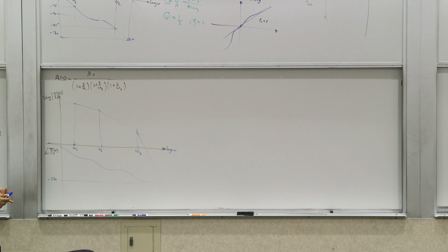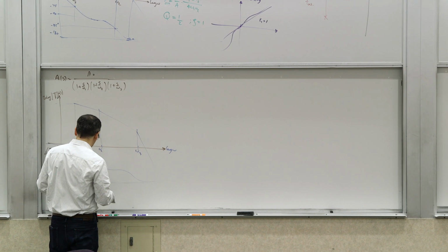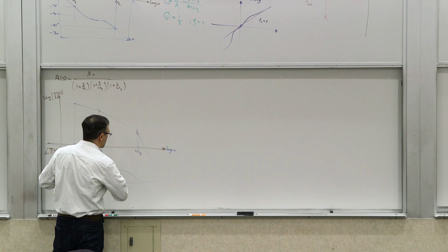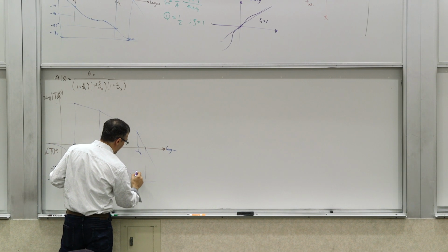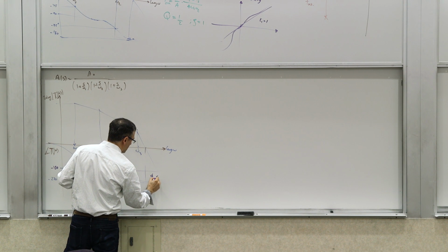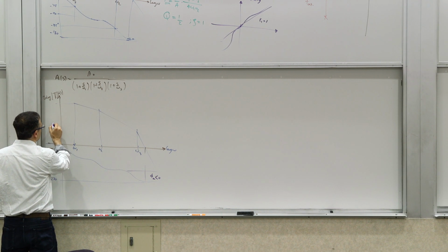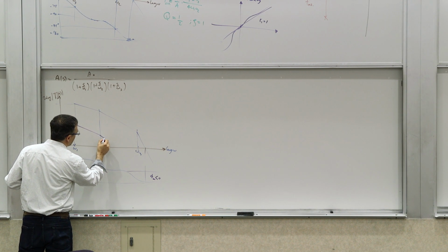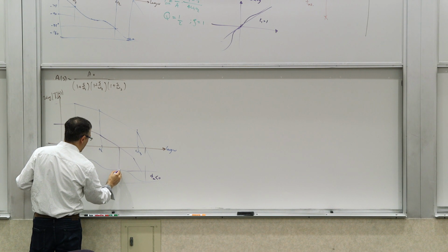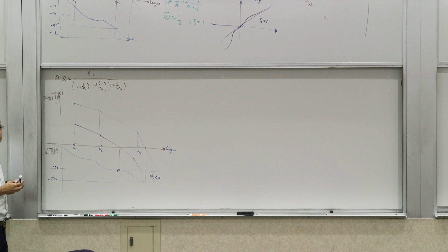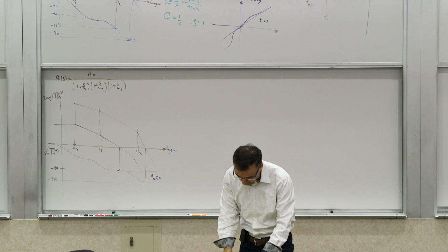So if I ask you what's the phase margin, you have to say the answer depends on where you cross the unity frequency. In this case, if this were actually our unity gain frequency, this is negative 180, so you actually have negative phase margin in this picture. Now, if we were looking at the same plot with reduced magnitude, if f were smaller, for example, and we were cutting across here, then you're looking at a tiny phase margin, depending on where it is. It could be positive or negative.